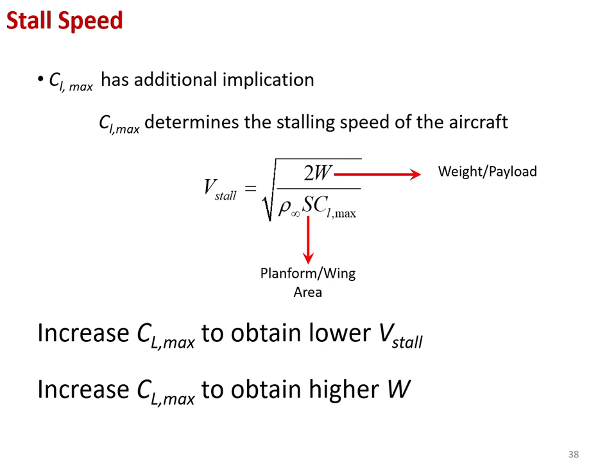The stall velocity is essentially the velocity at which you're going to get the maximum lift coefficient. And since after the stall, if you try to increase the velocity further, there will be a sharp decrease in the lift coefficient, which will cause a sharp decrease in the lift itself, and this balance between weight and lift is not going to exist anymore, which essentially means that you're going to lose altitude.